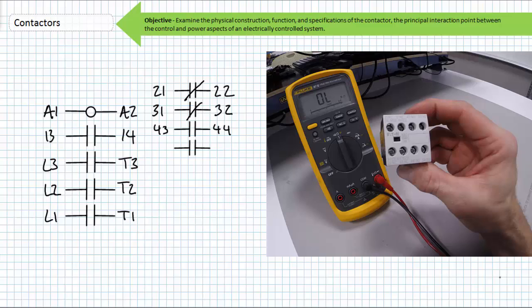This is the fourth set of auxiliary contacts associated with this contactor, so the first digit of these terminals is given the number 4. Since it is a normally open switch, it is assigned 3, 4 for the second digit, for terminals of 4-3 to 4-4.